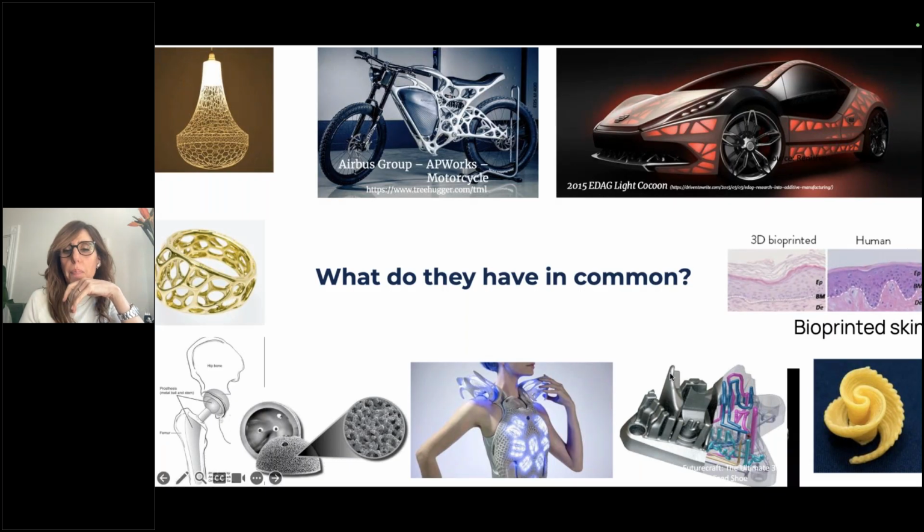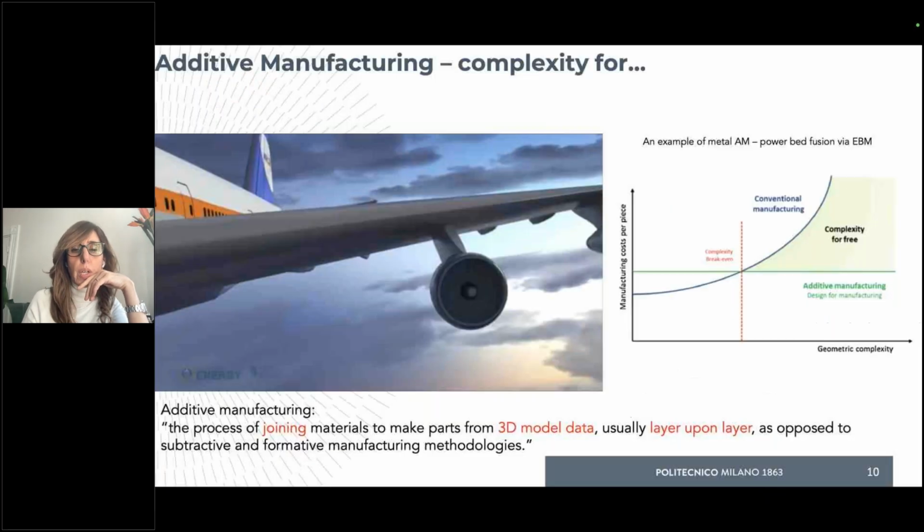And also in molds, which means machinery, you see the example that I'm trying to show at the bottom with all these channels with many different colors. This is called conformal cooling, which means that I can create this empty shape and channels inside the mold quite easily. I cannot do this type of complex channels with any other technologies. And usually this means that I'm able at the end to make a mold that is long lasting and has a better performance in the part that is being produced. And so there are a lot of opportunities also in the field of machinery for using this technology.